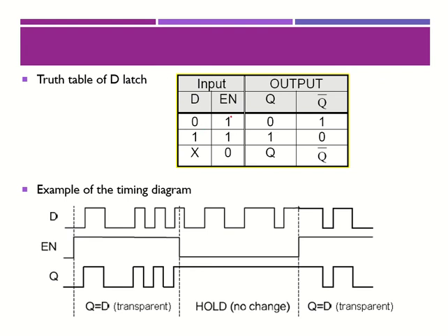So whenever you have an enable of 1, with D of 0 or 1, 0 will give a Q of 0, and whenever you have a 1, this will become 1, repeating exactly the same value. But when your enable is 0, this will become a hold. So it doesn't care about the situation of D, so this always becomes the previous data.